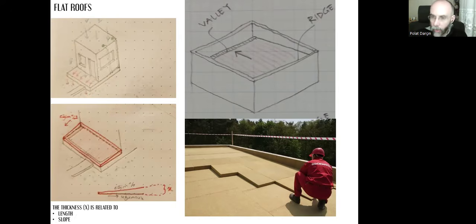Instead of concrete, I can use heat insulation panels, which are produced with these increasing thicknesses. As you can see, as we place the heat insulation, we will be providing a sufficient heat insulation, and also we will be creating a sloped surface for our flat roof so that we can direct the water towards the drainage system. This will be a better option.